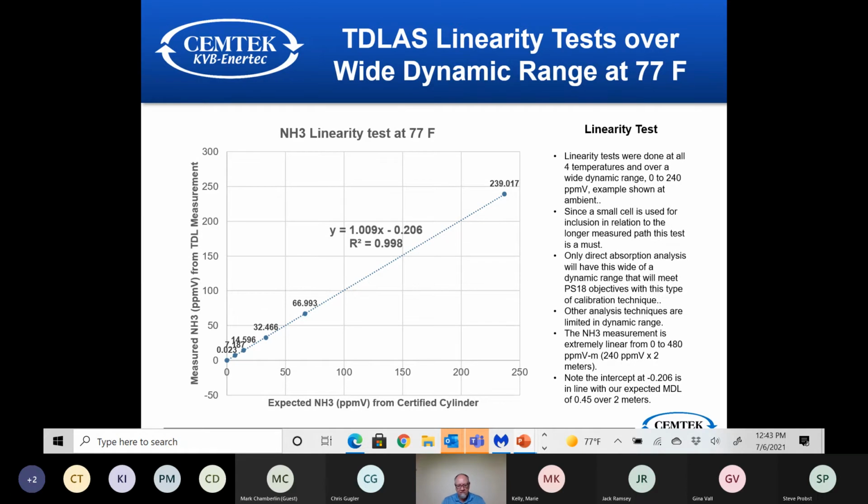The customer wanted both systems installed because they got a very, very strict ammonia slip limit. If they go over 5 ppm, they have to shut down, so they wanted a backup of the two systems. Their differential NOx has been down multiple times. Our laser hasn't been down once. So they still use both. They just want to be sure. But that's been about 7 years now, and they have almost no downtime on that laser because there's just no components to fail. And they just clean the optics when the unit's down, so it's always running, giving them data.